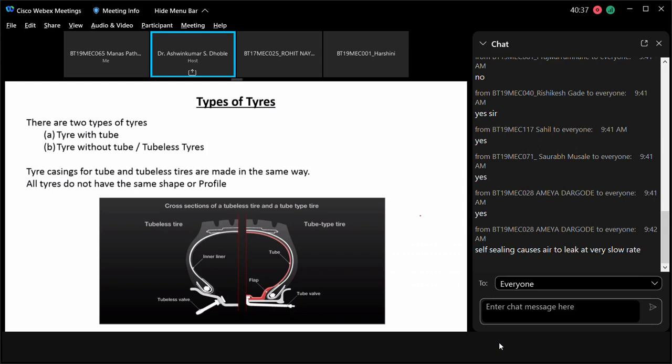So in my opinion, one should go for tire with tubes rather than the tubeless tire, because puncture repair is not that simple. By chance if it gets punctured, you can fit the stepney, but repairing is slightly difficult in the tubeless tire because you have to take that piercing tool, put the rubber into it, pierce it into the tire, take it out and make a seal. So that's a cold puncture basically, whereas here you can have the hot puncture.